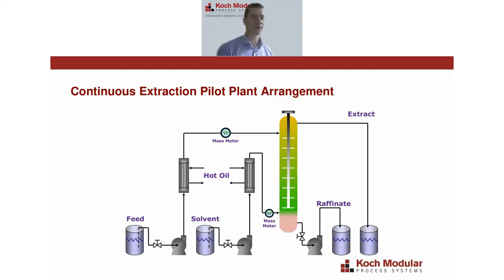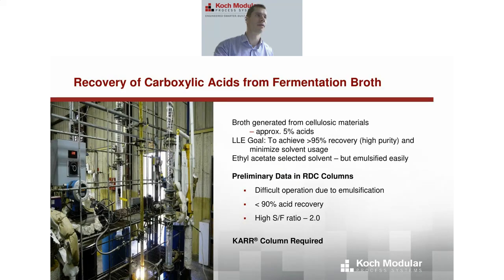Also the impact of coalescing on the internals, that's something else we can look at. And also emulsion bands, entrainment, and rag layers, as I discussed earlier. So there's a huge benefit to testing in glass, which is what we do, I would say 95% of the time. So now I'm going to go through the pilot test case study that I discussed earlier.